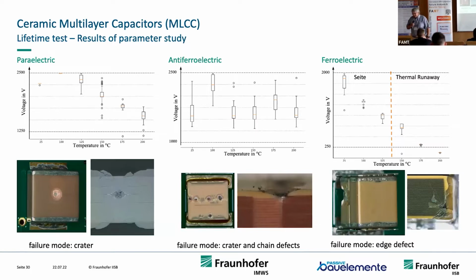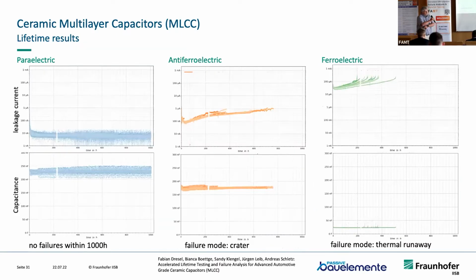A typical experiment for us is to have the capacitors tested, for example, up to 2,500 volts at different temperatures. See when they fail, and look at which failure mode is attributed to this. We do this with different materials and try to find out a systematic behind it, but we are not always successful in this, especially on the real products out in the market, capacitors and devices.